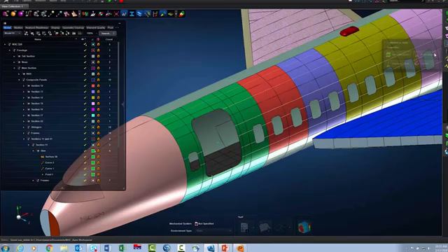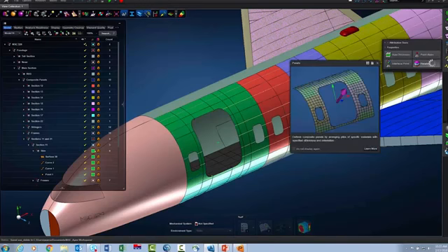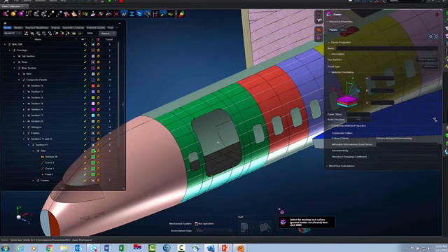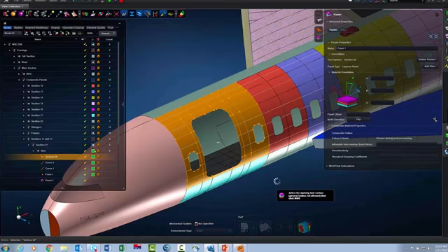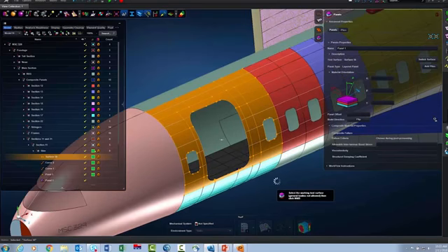Now, the composite panel in Apex is a special object that's going to store a lot of information about your layup. It's the composite panel that's actually going to manage the zones for you, manage the offsets for you. It's going to manage the layup. And in particular, what we're going to learn is that this panel itself is actually representing the tooling surface. That's how we're able to manage the offsets, especially, so easily and so automatically. So I have selected that geometric surface as my panel. This is going to be the tooling surface that I'm going to be working with.